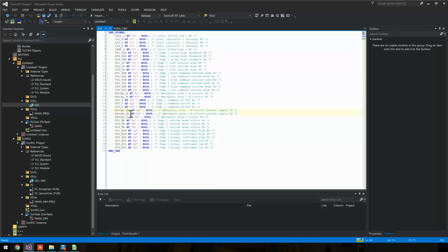There's redundancy here, and then wire that one to the actual emergency stop button. And if everything's okay and no one's pushed the emergency stop button, the 24 volts will return here. So that means that for the emergency stop to be okay, no one has pushed the button and the PLC is running, everything's okay, and the output card is working, so it's outputting 24 volts to the emergency stop. Otherwise, it's not okay.